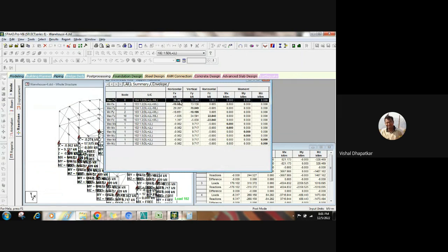during that time the bolt will not have any shear on it, because the compression is such that whatever shear is there will be nullified by the friction between the base plate and the pedestal. Now for this case, this is purely tension, right? When there is tension, the bolt will have this direct tension as well as this shear. So these two forces have to be resisted by the bolts, right?